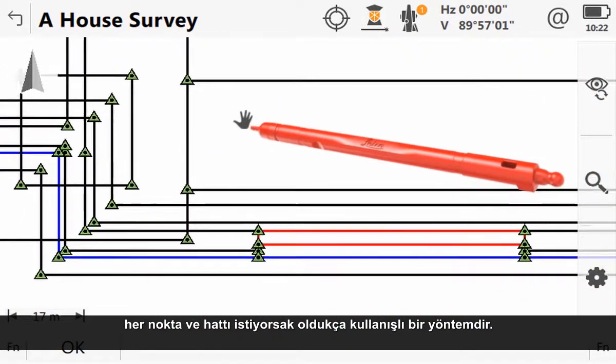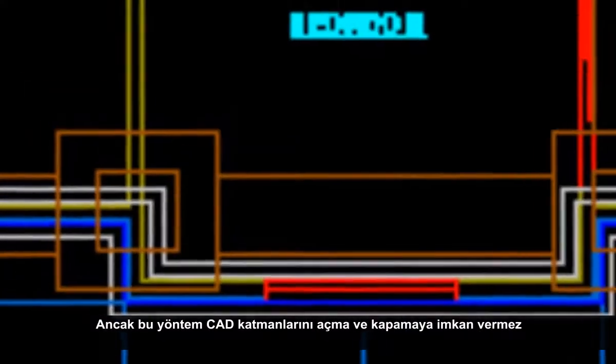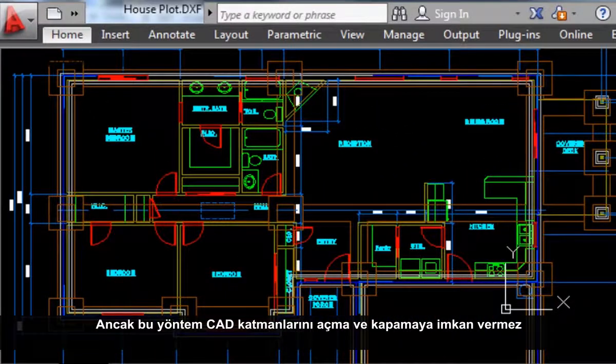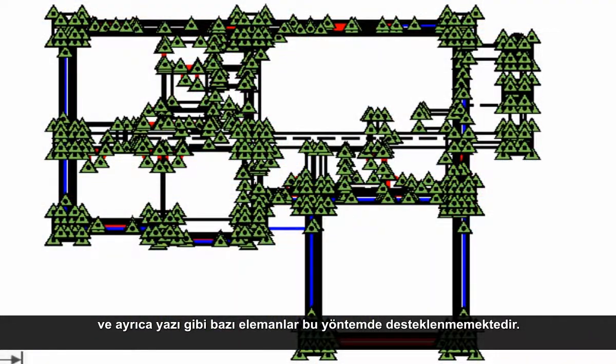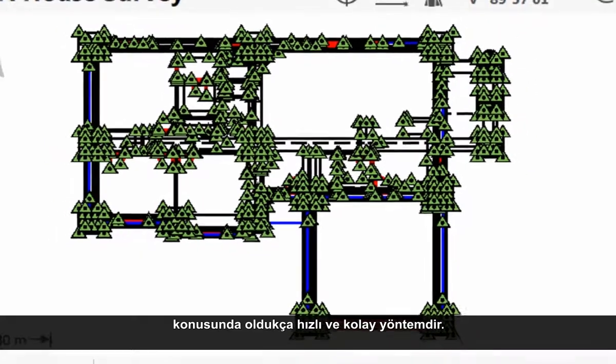This straightforward method of importing an entire DXF file straight into our job is very useful if we want to interact with every single point and line from the DXF file. However, this method does not allow us to switch different parts of the DXF file on and off, making use of CAD layers. And also, there are some elements that are not supported by this method, such as text. So, in effect, this method can be thought of as a really quick and easy way to get all of the points and lines from a DXF format into one of our jobs.